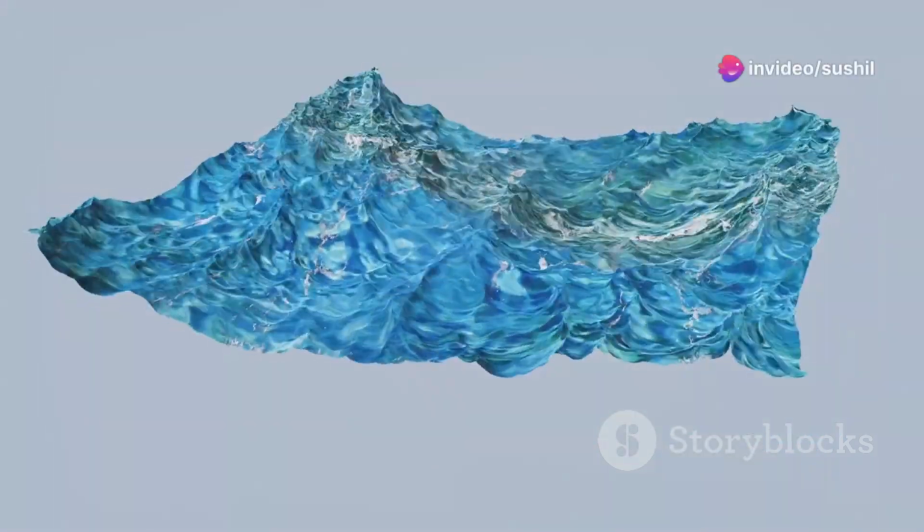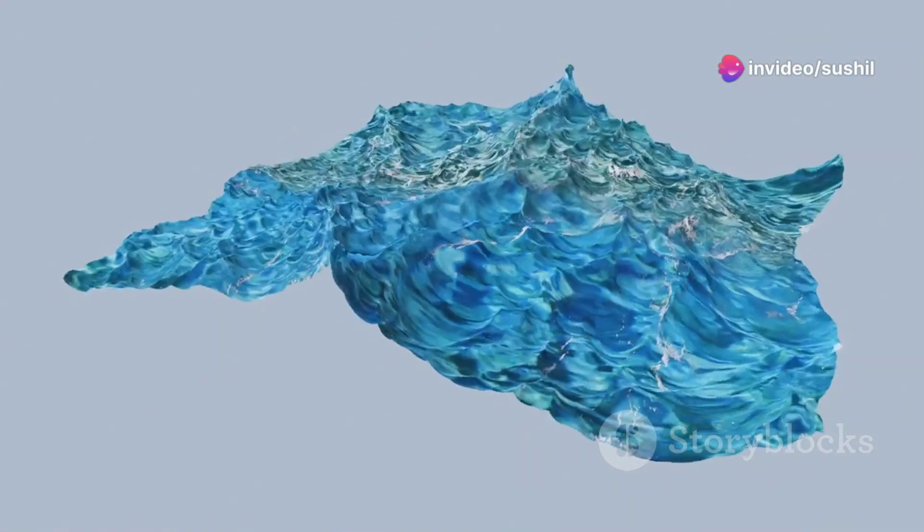Imagine a tube bent into an L shape, with one end facing directly into the oncoming flow. This is the basic design of a pitot tube. As the fluid enters the tube's opening, it comes to a stop at a point called the stagnation point. At this point, the fluid's velocity is zero, and its pressure is at its maximum, known as stagnation pressure.